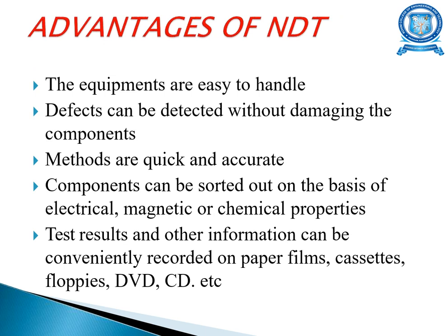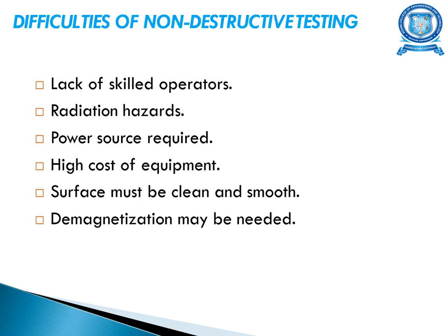Test results and other information can be recorded on paper, films, cassettes, floppies, DVDs, CDs, etc. And the difficulties of non-destructive testing are that skilled operators may not be available, radiation hazards are there, a power source is required, and the high cost of equipment is a difficulty. The surface must be clean and smooth, and demagnetization of components is needed in magnetic particle testing.